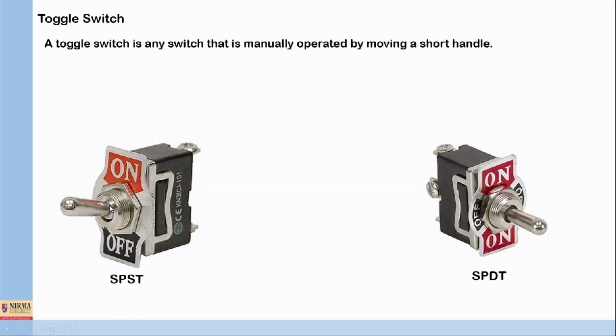This is an SPST switch, which is very similar to the normal switch we are using for the bulb and fan. And this is an SPDT switch, which is very similar to the staircase wiring switches or the go-down wiring switches. Okay, so in SPST, if we switch it off, then it will be on. Down means off. Similarly, SPDT has two on conditions. The middle one is off. It will go to off. That will be on, and that will be connected to one circuit. And it will be toggle down. So toggle down, what will happen? It will connect to another circuit to make it on.